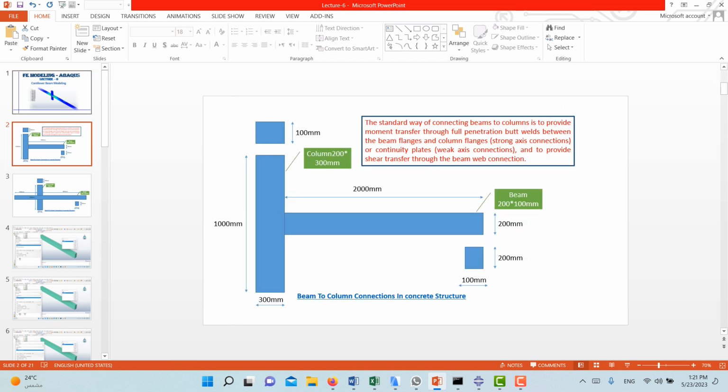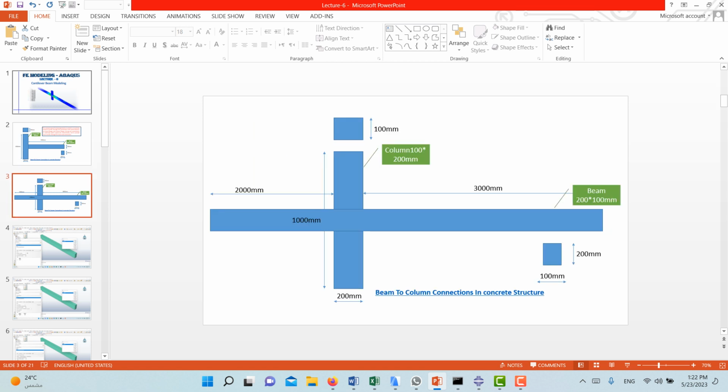Since we finished the drawing options in ABAQUS and created the model, as you see on the screen, this is a cantilever, just on one side, and here I can deliver both sides, which is a different distance, in order to find the comparison between the long and short span for the cantilever under displacement or under uniform load. It could be a concentrated load.